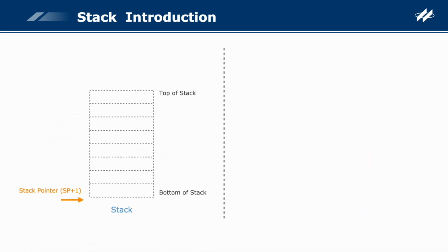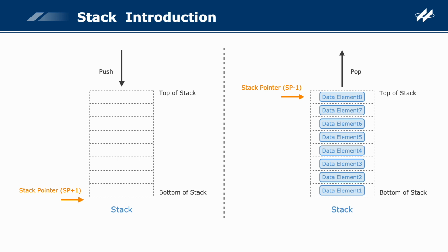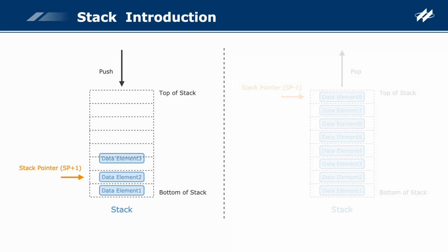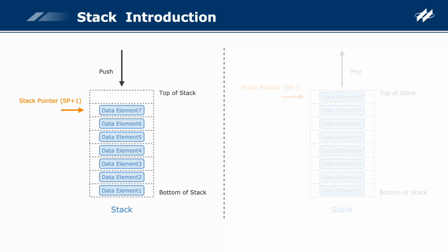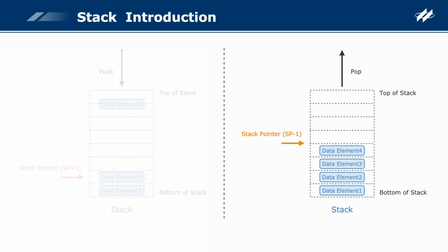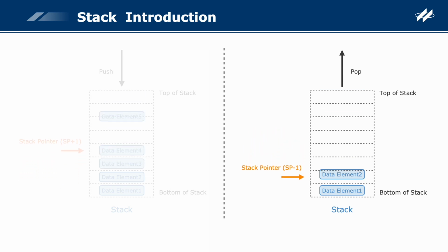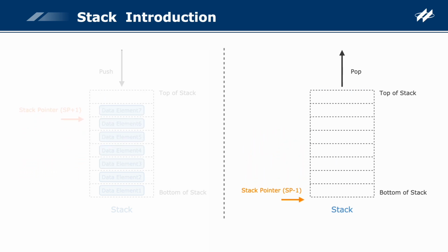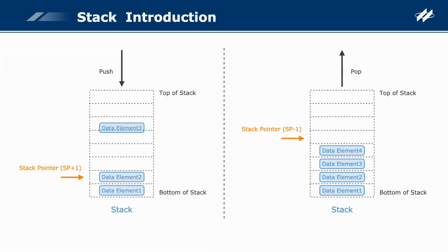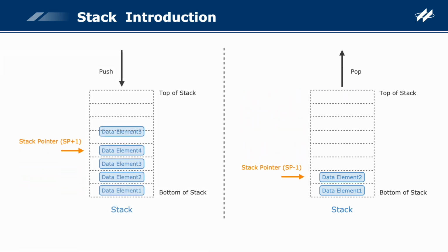The two most important stack operations are the push and pop. Let's understand the push operation. An element is added first and then the stack pointer is increased by 1. In the pop operation, however, the contents specified by the stack pointer are sent to the destination location, and then the stack pointer is decreased by 1. These two operations implement data insertion and removal.